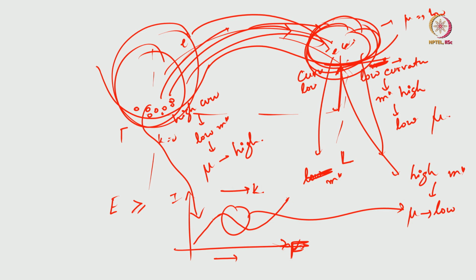You cannot expect silicon or germanium to do that, but gallium arsenide can be used, because its E-k structure allows electrons to be transported from one valley to another valley of different curvatures, which is to your advantage, and using that you can experience a negative differential resistance, which is why you get a curve of electric current density versus electric field which exhibits a negative differential resistance, okay.